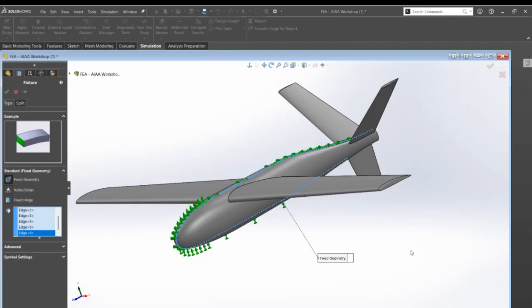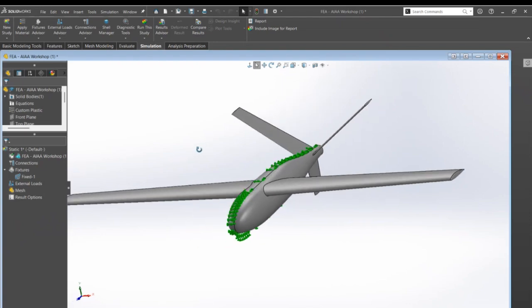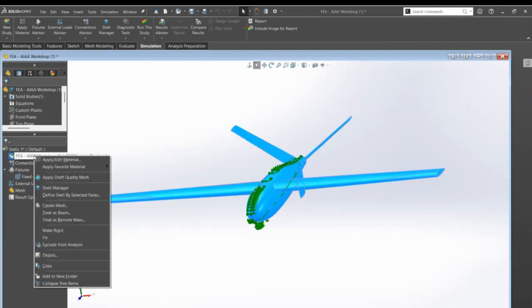Okay, cool. I think everybody is caught up for the most part. So we'll go ahead and click yes. And now something that you always have to do is set the material. I think when you downloaded it, you might have already had custom plastic, and this is actually a custom plastic that's set to be PLA because that's what we're going to be making it out of. However, you might make it out of something different.